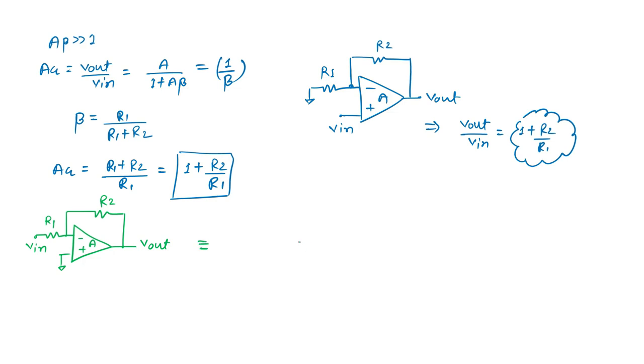This cannot be directly analyzed using negative feedback, but the structure can be drawn this way: this terminal is grounded and I take the output across the end of R2, with R1 as the feedback. It is not exactly a negative feedback system because this node is not 0; it is at some value related to the input voltage.